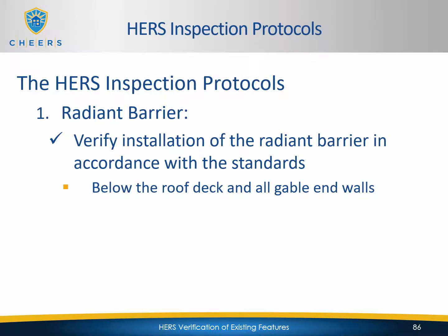For radiant barrier, you just want to verify that the installation is in accordance with the standards, which is below the roof deck, and all gable end walls also have to be wrapped in radiant barrier, just like we had talked about in the Title 24 overview.